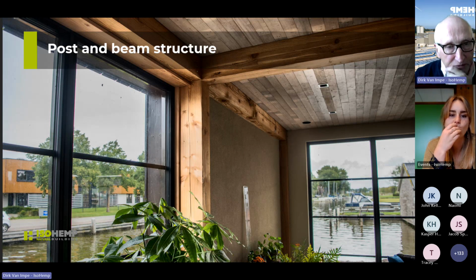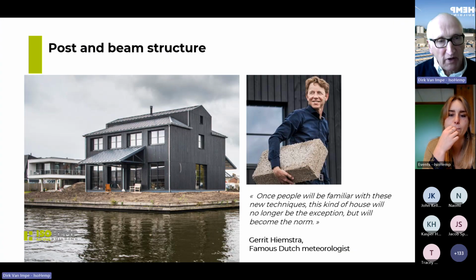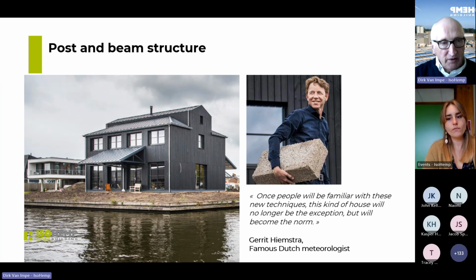Here you see the inside. And let's go back to this one, because you see it's a wooden cladding. And this shows also the importance of the heat storage capacity of the blocks. This is a wooden construction, very lightweight. If you insulate this with lightweight insulation materials like glass wool or the insulating foams, because it's all black, with a lot of windows, it will be hard to bear in summertime. The temperature will go up very quickly, and you need cooling at that moment.